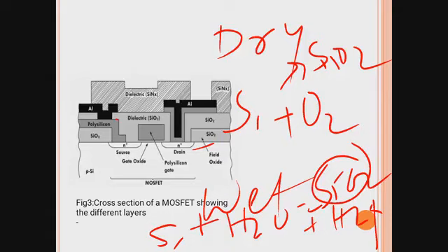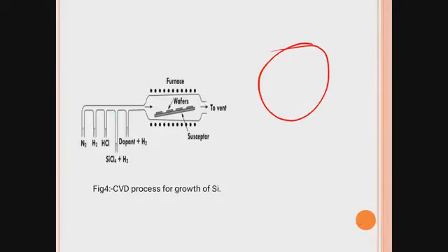And here the silicon dioxide layer is formed, as I already told, on the surface by consuming the underlying silicon layer. For further oxidation, the oxidizing species used are oxygen and H2O, which have to diffuse through the oxide to reach the silicon surface.